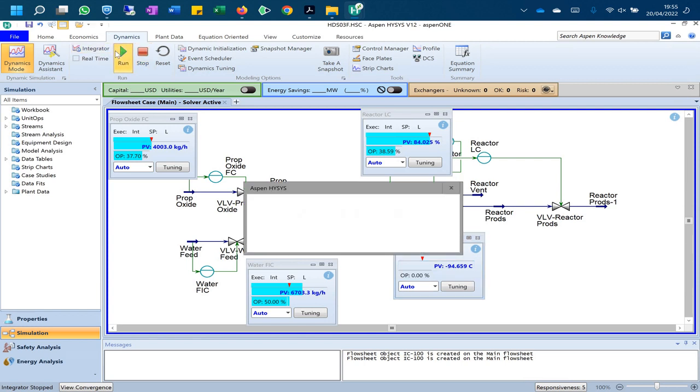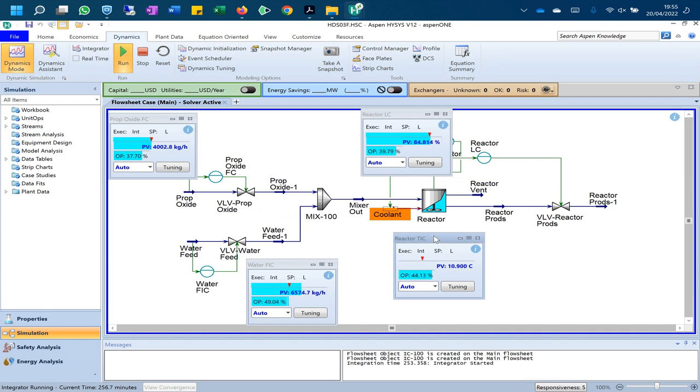When I run the simulation, no dynamic assistant, the system of course goes to maximum output. This means that the coolant is set to 0, but since temperature is so low, 10 degrees, the reaction does not take place, no exothermic enthalpy is released, and temperature cannot go to a higher value.